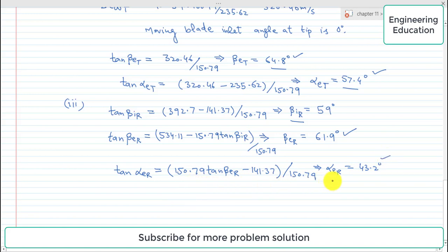So this is basically the fixed blade angle at inlet at the root. Similarly for alpha IR, tangent alpha IR is equal to 392.7 divided by 150.79. Simplifying this and solving for alpha IR, we get 69 degree, and this alpha IR is basically the fixed blade angle at the root.